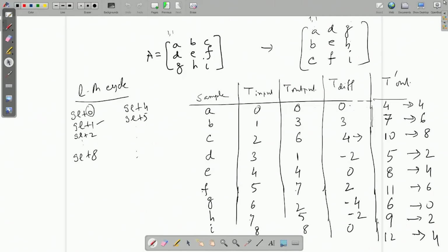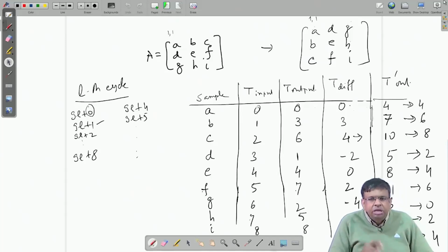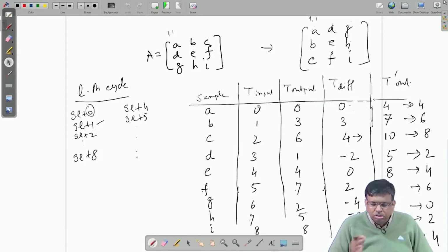Now, suppose this matrix A is coming in cycle after cycle, new and new matrices are given to the system. The system will read, and then write a new matrix which is the transpose of the matrix read in that particular cycle. Suppose in a particular cycle, say the Lth cycle, the system reads this. It takes the whole of the Lth input cycle and divides it into 9 sub cycles, that is 9 system cycles, which is faster, because each input cycle is divided into 9 system cycles. So the system clock goes up by 9.